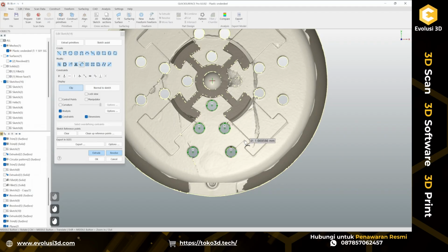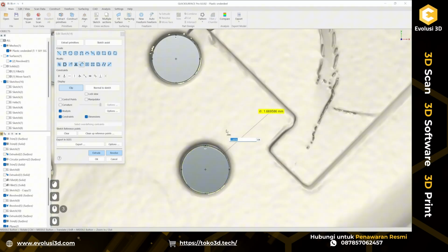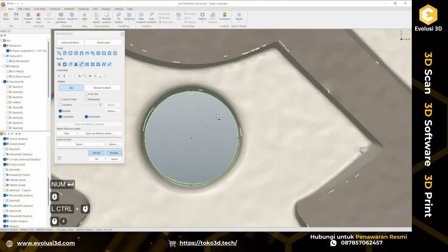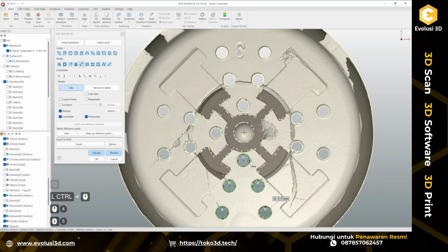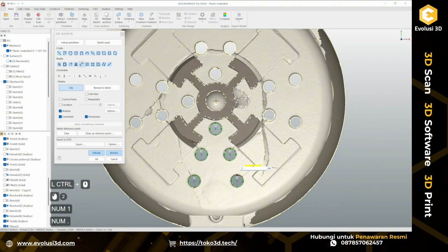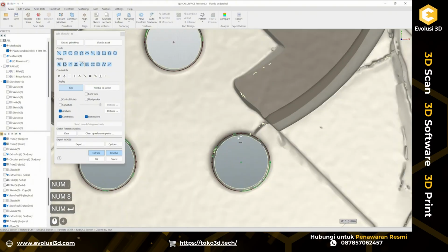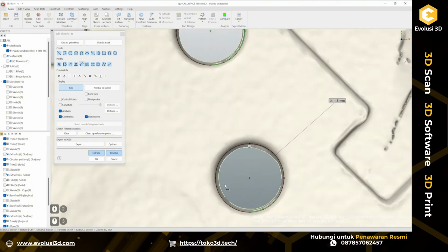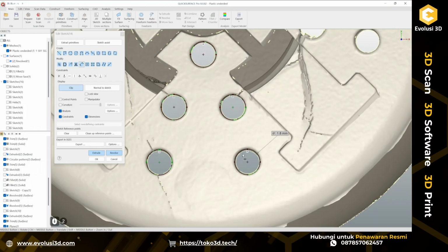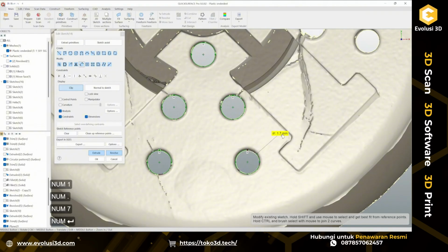So at this point, I would like to make all of them equal diameter. So probably I'll want to set this diameter to something like 0.7 maybe. Well, let's say this is 0.8. So we can see we're getting a little bit further away, but as I figured out previously, this was our parting line for draft. Oh, actually, I will go back to 0.7 to have some average.